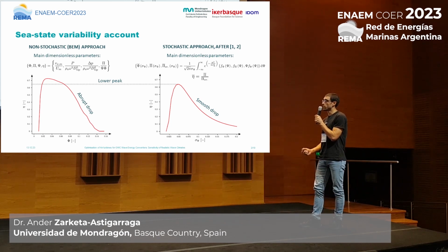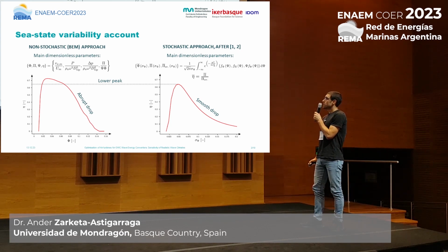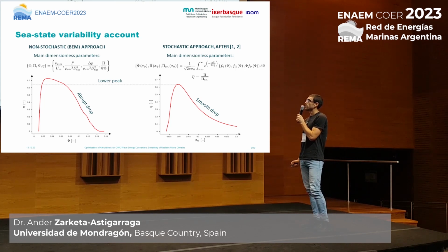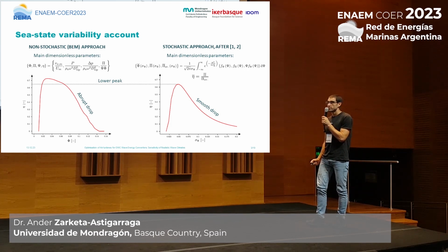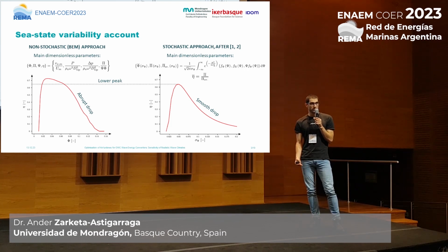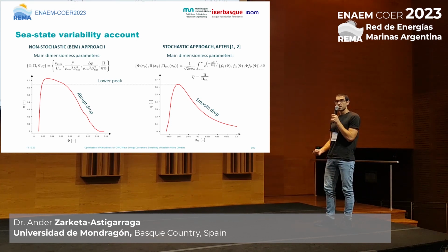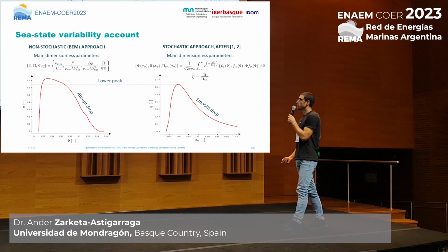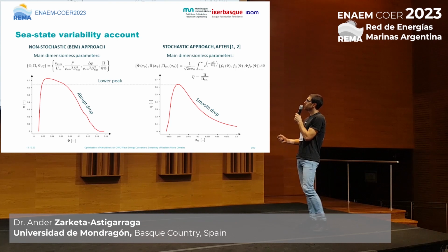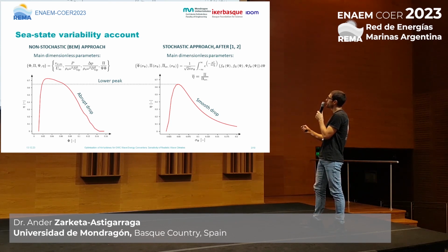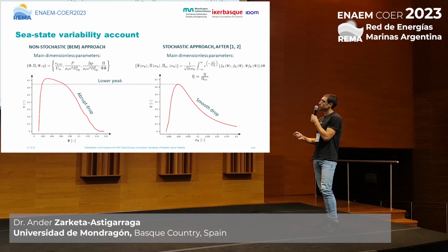Now, in order to account for such variability, we follow the approach adopted by Falcao et al., who say that you can calculate a sort of averaged dimensionless parameters whenever the sea state is liable to be described statistically. We will assume that such is the case, and that we have a Gaussian PDF for the dimensionless pressure variations in the chamber. With the convolution-like operation that we are taking here, we introduce just the average counterparts of these parameters, okay?